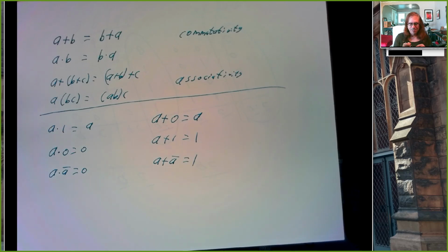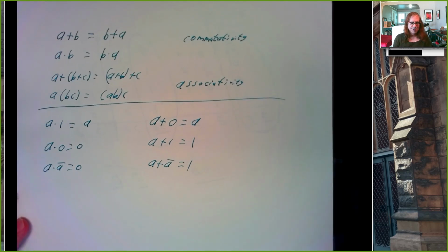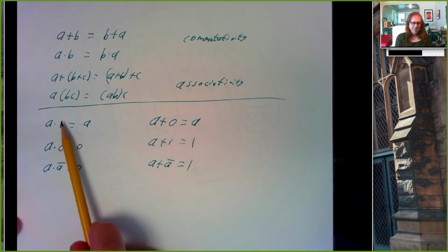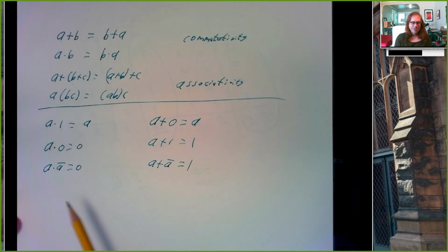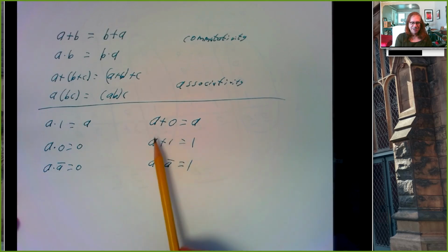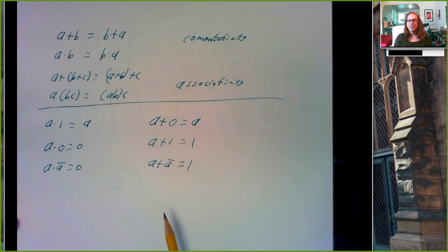And you may have noticed or start noticing there's some kind of relationship here, right? I can take my 1s and 0s over here and replace them with 0s and 1s over here. And I change my ANDs into ORs, and I mostly get the same thing by doing these replacements. And so this gets into the idea of duals and dualism. And dualism is a whole topic in itself. It's a whole philosophy, actually.